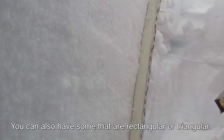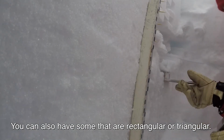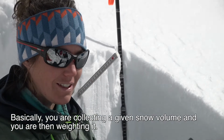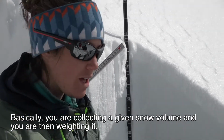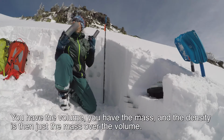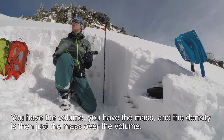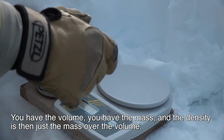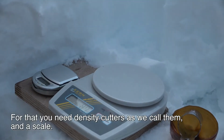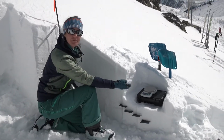You can also have some that are rectangular or triangular, different shapes exist. But basically you are collecting a given snow volume and then weighing it. So you have the volume, you have the mass, and the density is then just the mass over the volume. For that you need density cutters, as we call them, and a scale.